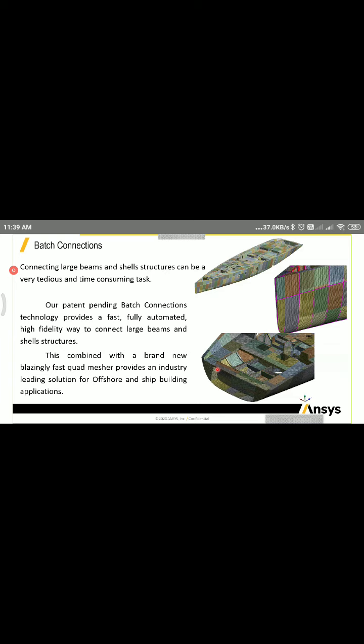So in such scenarios, if your thickness to the other two dimensions ratio is more than 150 or 120, you can use the mid surfacing or the shell approach. Similarly, if you have one dimension which is very long compared to the other two dimensions, you can go with the beam approach, right? Because as in the previous thing we discussed, if you want to model the smaller thickness, you may want to have at least 2 or 3 cells through thickness. And that will be very huge in terms of capturing the geometry, and mesh count will drastically increase.